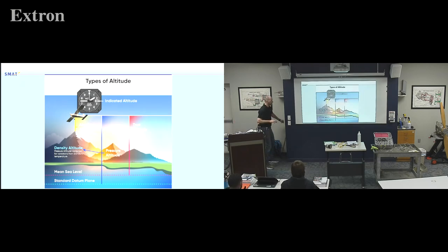So quick review, we have 4 altitudes. We've got absolute, where you absolutely hit the mountain, as indicated by our radar altimeter. There's actually 5. We've got true altitude, which is saying above mean sea level. That's what we adjust our altimeter to read when we're flying, unless we're up in Class A airspace, then we just adjust it to pressure altitude.